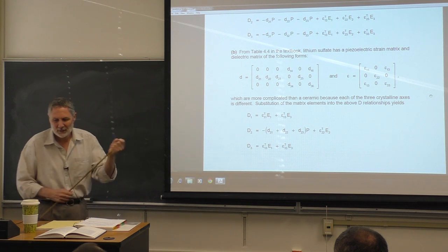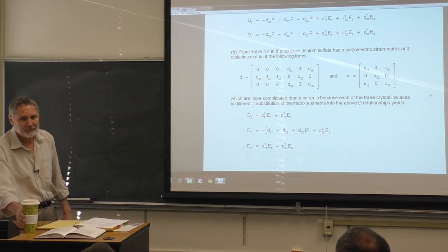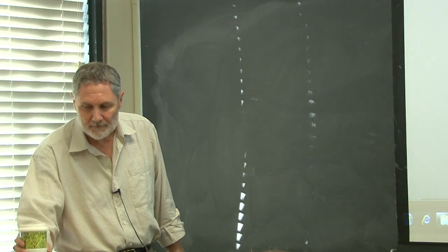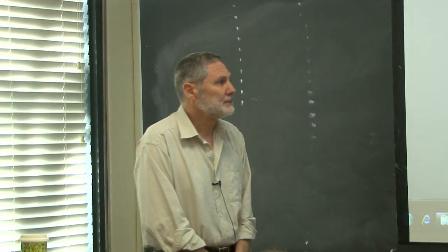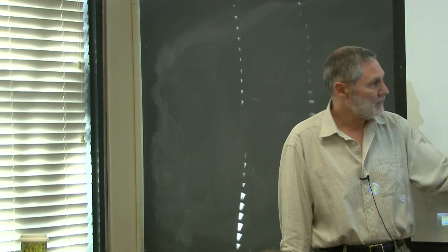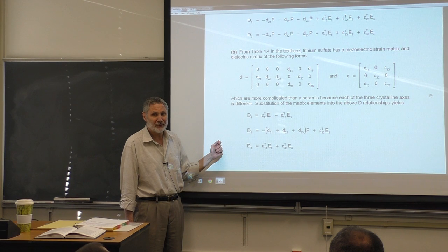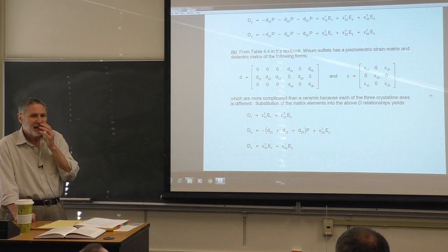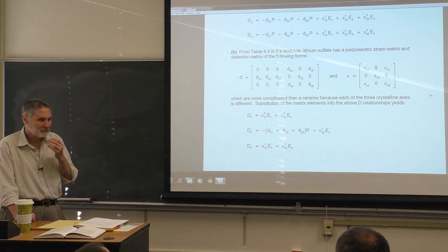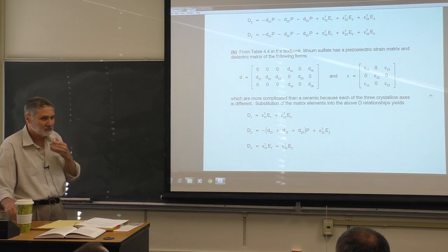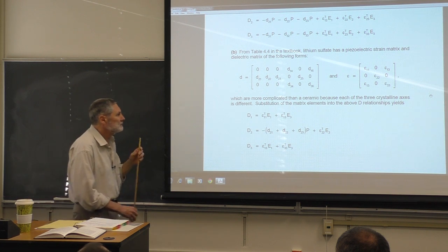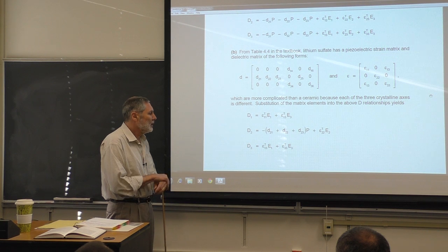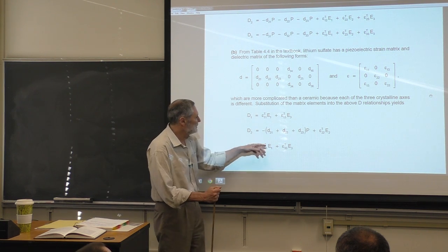I guess my general question is, we're trying to get pressure signal to produce a voltage in order to use that. And in the 1 and 3 direction, it doesn't seem like that's possible based on these. Not here, and not for uniform fields. Right, here it's impossible. So solving this without the problem set, I would have thought, okay, there's no relationship between pressure and the 1 and 3 directions, so I would electrode the 2 directions. Oh, I see what you're showing mathematically because there's no P down here.